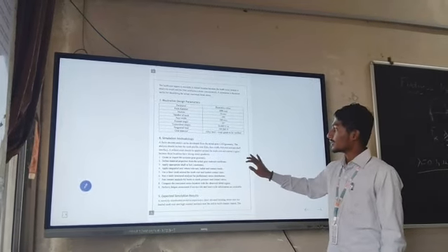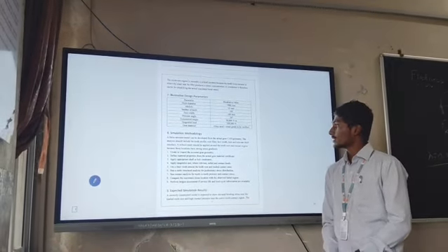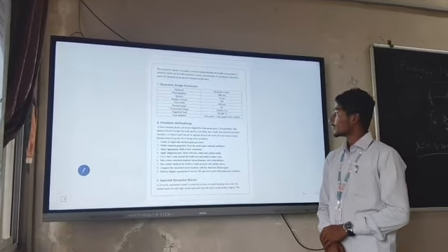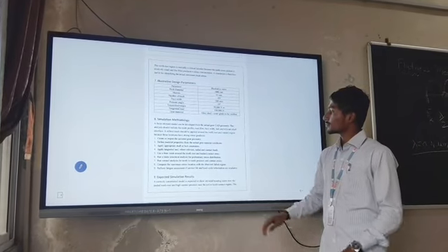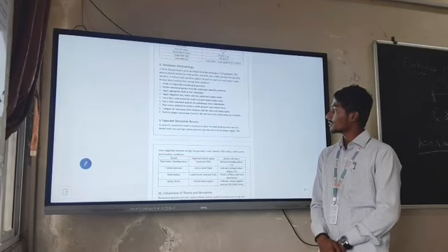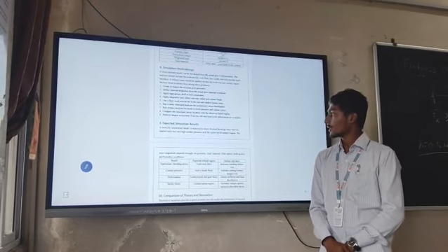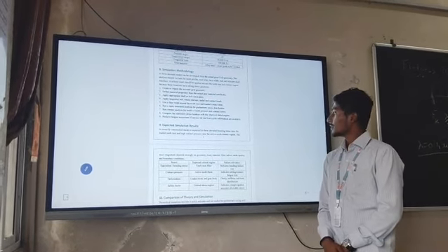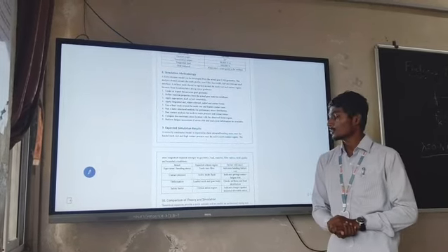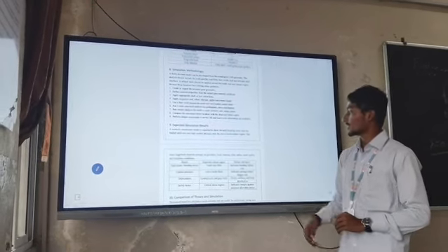Next one is simulation methodology. A finite element model can be developed from the actual CAD geometry. The analysis should include the tooth profile, root fillet, face width, hub and relevant shaft interface. Next is the expected simulation result. A correctly constructed model is expected to show elevated bending stress near the loaded tooth root and high contact pressure near the active contact region. The exact magnitude depends strongly on geometry, load, material, fillet radius, mesh quality, and boundary conditions.